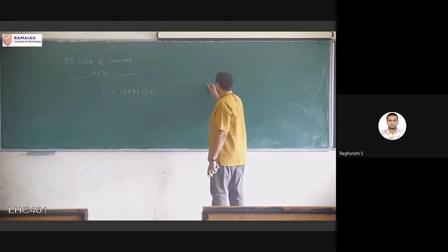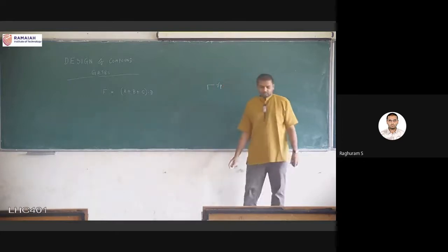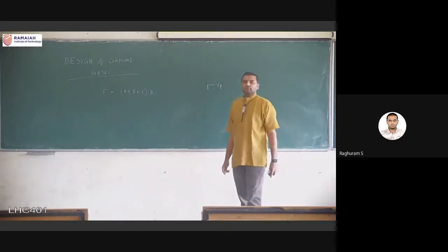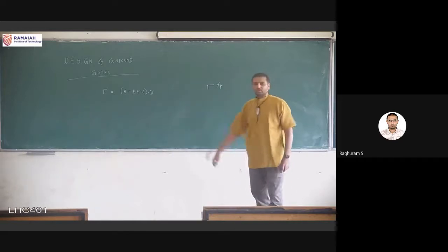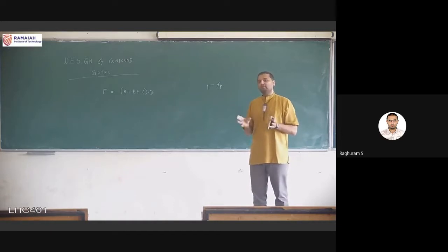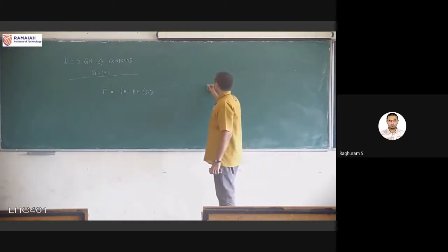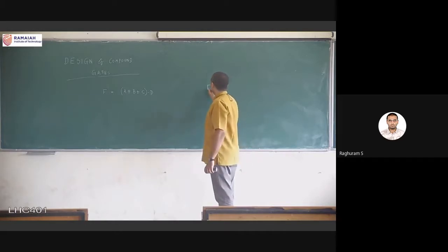As always, start with the pull down network. Sum of product or product of sums, that is also the question. Here we have two terms that are being multiplied with each other, so this is a product of sums, which means that it is only going to have one branch in the pull down network.